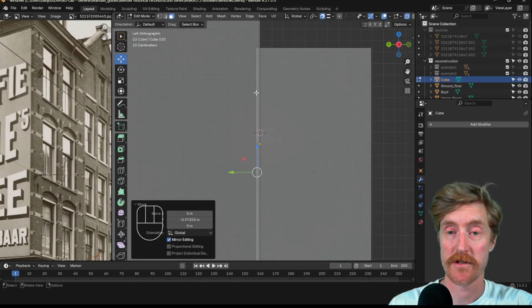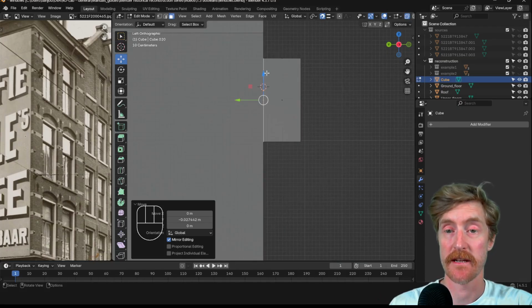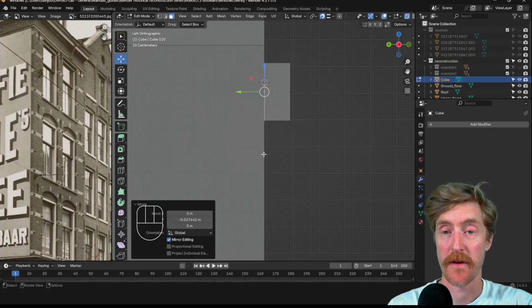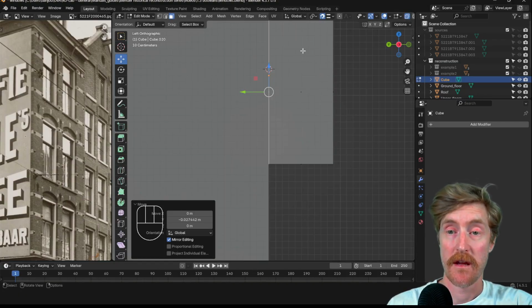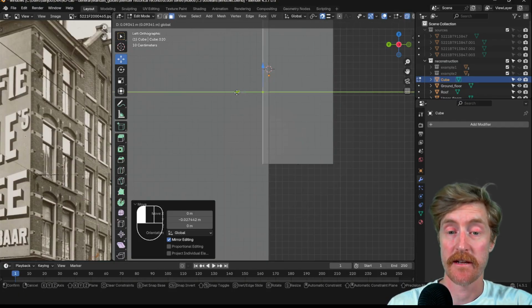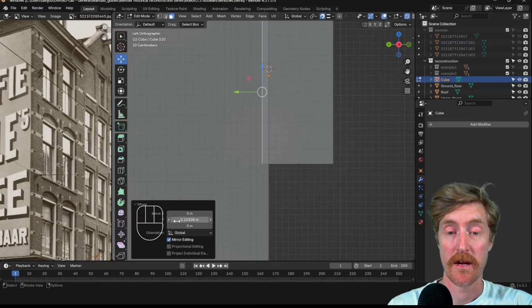I turn off the sources. Yeah, you see I was snapping to one of the architectural drawings. Now it's exactly aligned with the front face of the building. To get it 29 centimeters back, we just start dragging in this direction, and then over here at the lower left of the 3D modeling window, enlarge this, sort of the settings for the last tool that you used, and I can modify the distance.